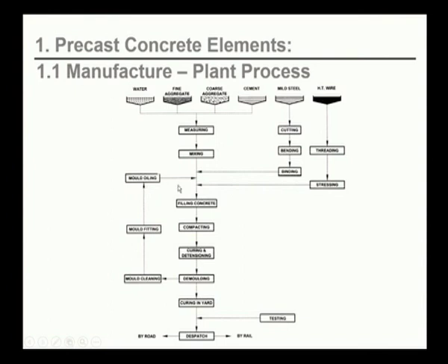In this case we have the molds, we have the concrete, and we have the cage made up of steel wires and mild steel bars put together in the shape of the form we want to put concrete into. So we take the mold, put all this together, and then fill concrete inside. Then compacting happens, the next step is curing and detensioning, then demolding.